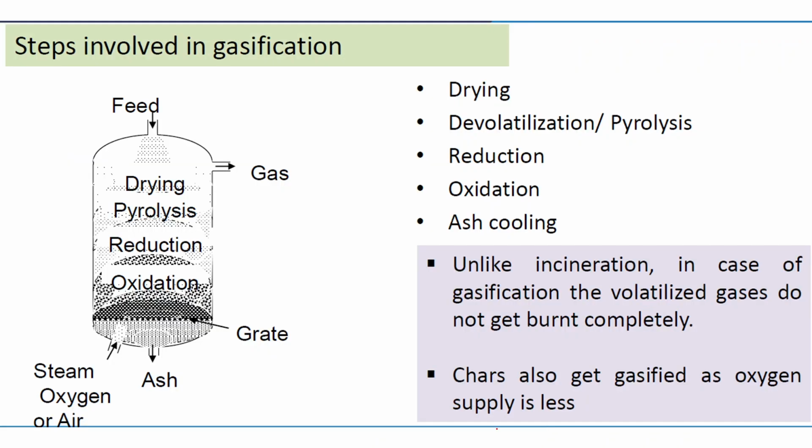Coming to the steps involved in gasification, we introduce the feed from the top and steam and oxygen from below. Oxidation takes place at the lower zone, then the reduction, then pyrolysis.